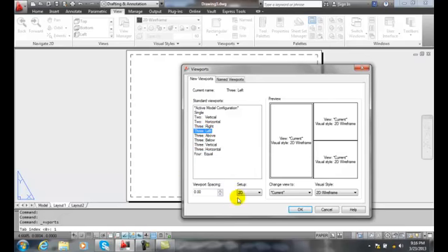And then down here I have a viewport spacing. So think of it as like the gutters of how far in between each viewport. I do recommend putting some spaces in. When they're at 0, they're hard to grab and stretch and manipulate. So I'll put some spacing in. I'll put like 0.5 for now, make sure we can easily see that, but typically I put around 1/4 inch, just there's something to grab.